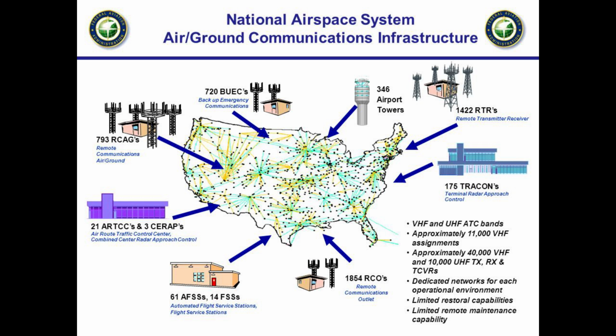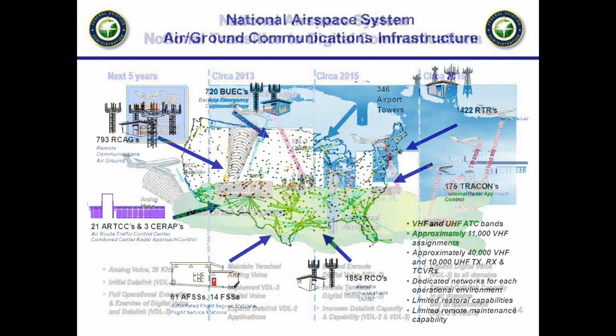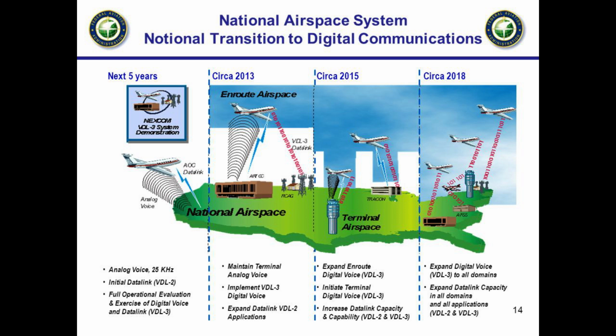GCOs are manufactured by different companies including ARINC and Avtec, each with different operating characteristics but with the ability to accomplish the same goal. This latest technology has proven to be an incredibly useful tool for communicating with the appropriate authorities when departing IFR from a non-towered airport. The GCO should help relieve the need to use the telephone to call ATC and the need to depart into marginal conditions just to achieve radio contact. GCO information is listed on airport charts and instrument approach charts with other communications frequencies. Signs may also be located on an airport to notify you of the frequency and proper usage.